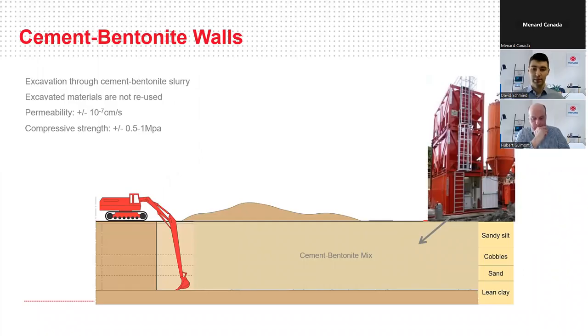We have a cement batching and we have a hydration tank for bentonite. We'll batch the two together and pump it out. Again, we can pump it about 1 kilometer, maybe a little bit less, maybe a little bit further. We can also add satellite pumping stations if we need to get a little bit extra distance in, and we're pouring the slurry directly at the working excavation phase. So as the excavator is excavating the wall, we're pouring the slurry directly in.